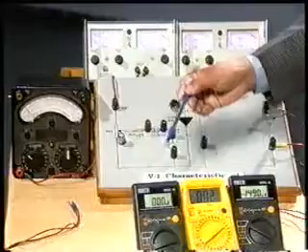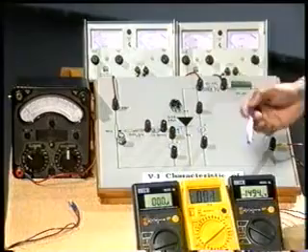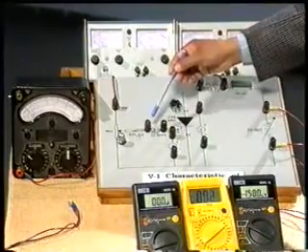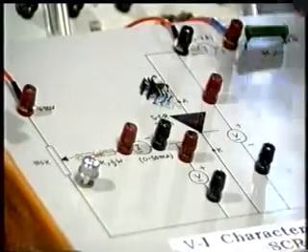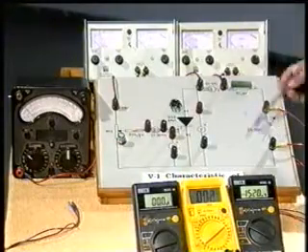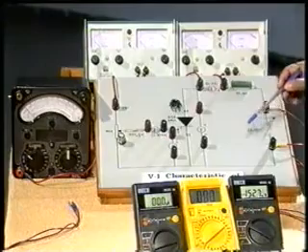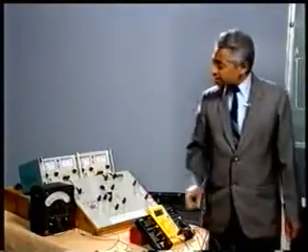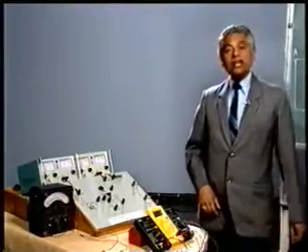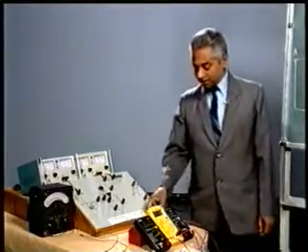In these two terminals, you find this is positive, this is negative. We are going to connect this multimeter as an ammeter, and what will it show? Yes, it will show the gate current. Now, this is all about the circuit we have rigged up for the verification of the VI characteristic of SCR. So now let us do the experiment, and first of all I am going to connect the multimeters.